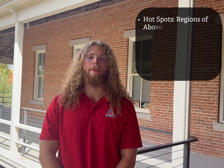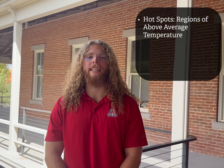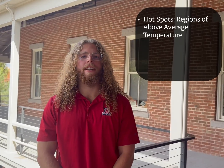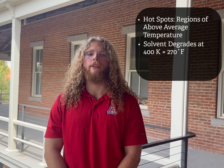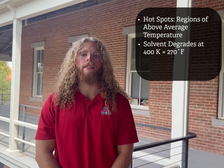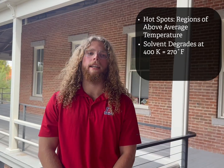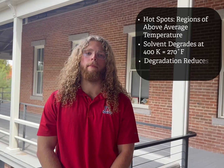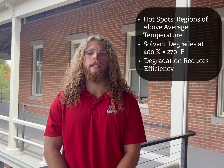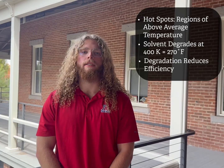We chose this design for a very specific reason. It helps prevent hotspots. Our solvent begins to degrade at around 400 Kelvin, so maintaining tight temperature control is critical. In reactors without strong mixing, you can get localized regions where the temperature is significantly higher than average, which can damage the solvent and reduce its effectiveness over time.